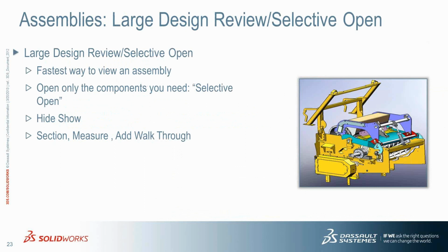There are tools out there in the industry that are there specifically for viewing large models, but also giving you the ability to review it with extra tools with other people. And SOLIDWORKS added this a couple of releases ago called Large Design Review. You have some extra capability. First of all, it is the fastest way to view an assembly. If you have large assemblies and you need to show somebody something, open it in Large Design Review.